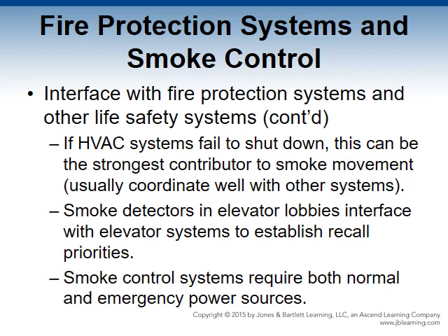Usual activation of automatic initiating devices starts the operation of the smoke control system. In some cases, any water flow or detection device will start the system. In other cases, the initiation device must be near or within the protected smoke control zone to initiate the smoke control. Manual activation is also required. Any HVAC system failing to shut down can be the strongest contributor to smoke movement. Most HVAC systems interface with other systems and detectors and shut down, close, or open and turn to control smoke movement.